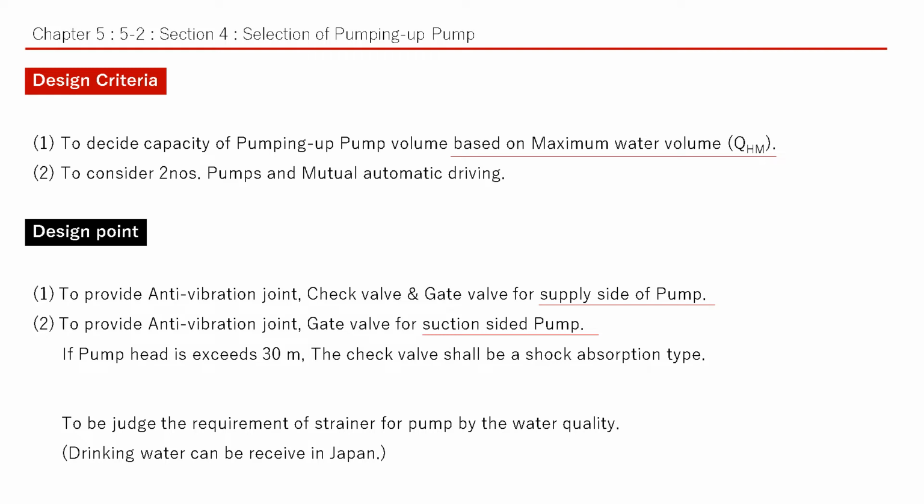Sometimes not clean water will be received from outside. In that case, we need to consider a strainer before the pump to protect it. In Japan, city water is already clean. That's why we normally do not consider strainers for pumps.